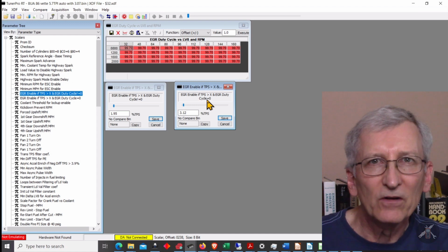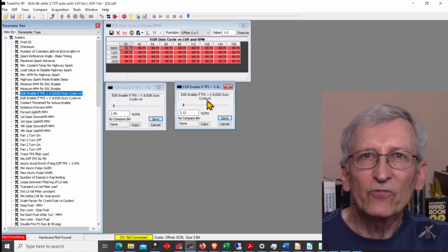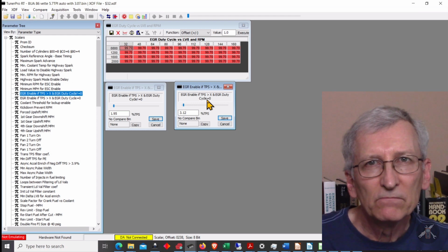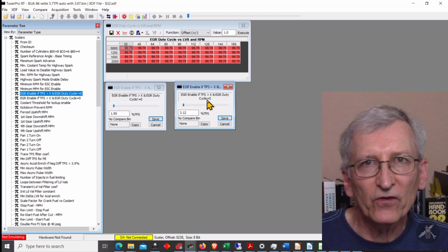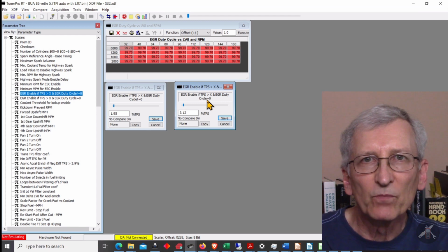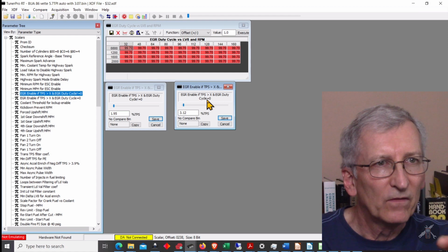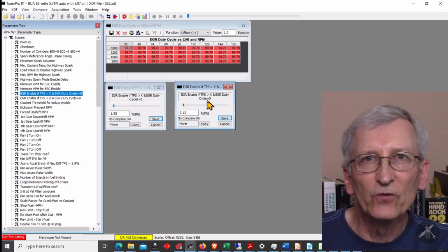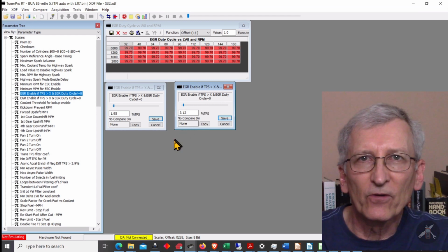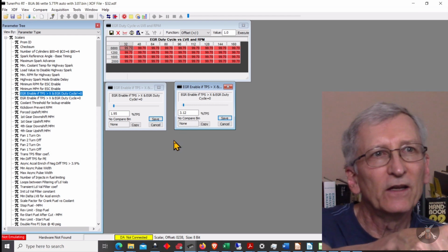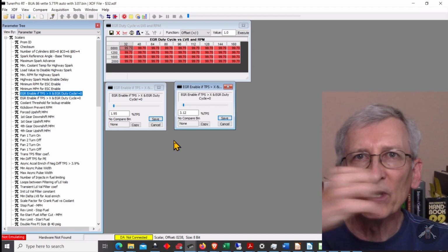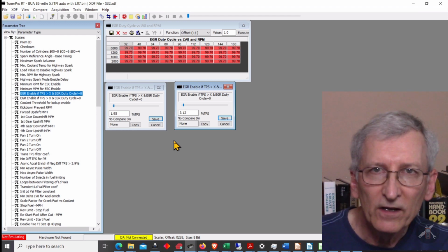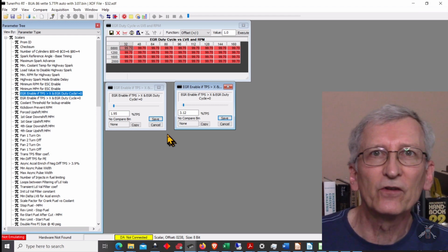So, to recap, you've got software in the controller that runs the engine, and it could run multiple different kinds of engines under that same part number controller, but your PROM will tell the software what calibration values to put into the software to make it run right. What should your idle speed be? It'll look at this chip, it'll take the value for idle speed and tell the software that's what I want it to idle at. And the software will say, oh, okay, and I've got a bunch of commands to do.